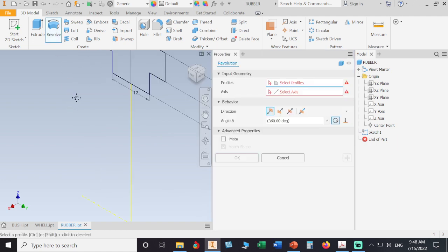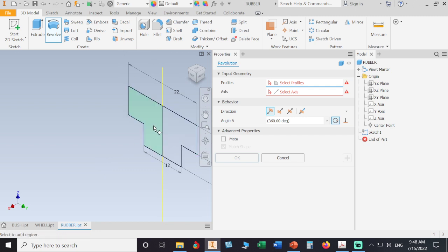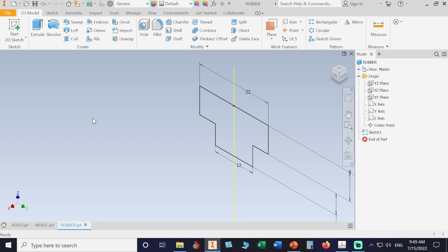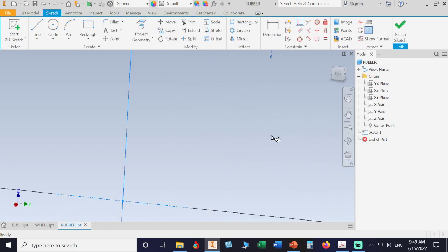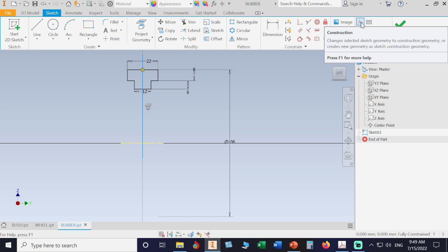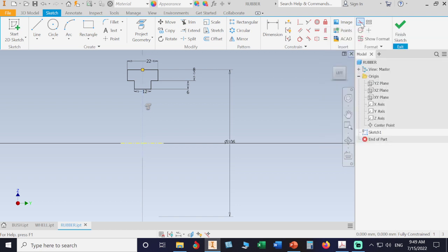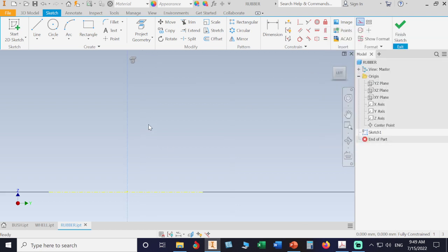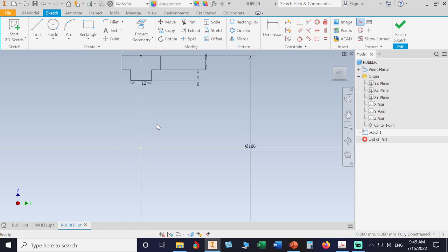You come here, you click, because it's a solid line, you divide it to two pieces. Can you see? How to fix this? I prefer to do it. Double click on the sketch again to edit it. Now, any lines or projected geometry that we don't need in our sketch, we click on them and change them to construction. Can you see construction? Now it's changed to dotted line.